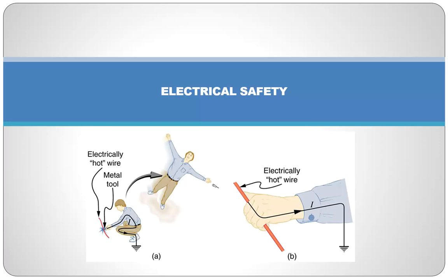Then your next risk comes from the heart itself. You get to about 70 milliamps across the heart, and it will cause the heart to depolarize without you telling it to. And so that can cause fibrillations. Bad. So the next danger is getting up to about 70 milliamps across the heart. The first one I talked about was just across the chest, making those intercostals tighten up. Less current required for that. Then across the heart, causing you to have fibrillations.